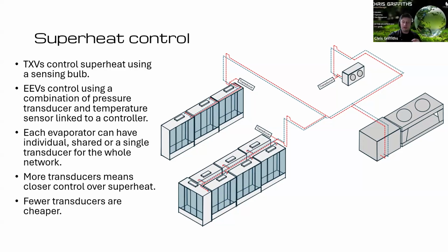Or you get what we call stepper valves, which will wind themselves in and wind themselves out to more closely match the amount of refrigerant which it needs to let through. So if it was 50%, basically it should wind up to be 50% of the openable area to allow 50% of refrigerant through. It doesn't quite work like that in terms of how fluid flows through a valve, but for the purpose of today, that's as accurate as we need to be.